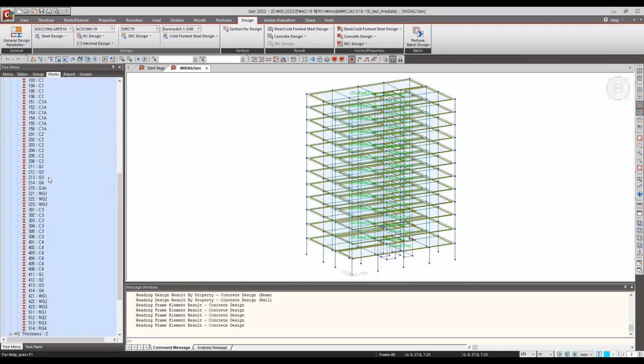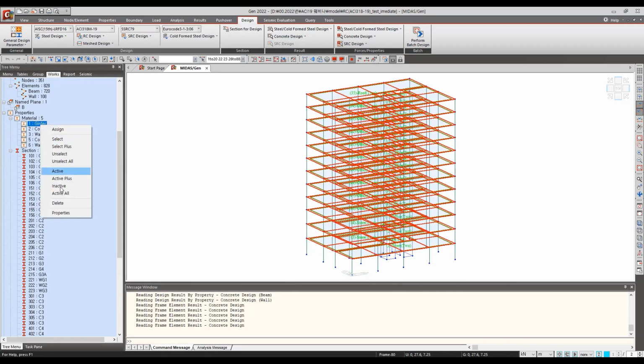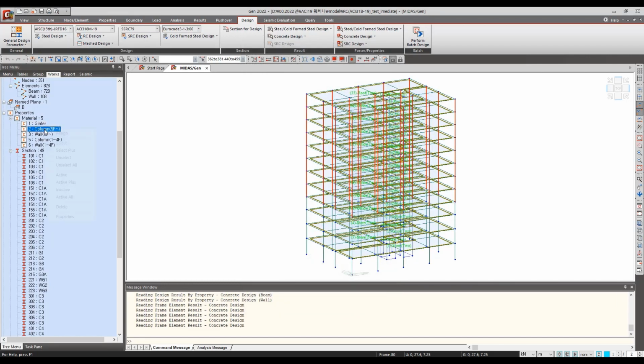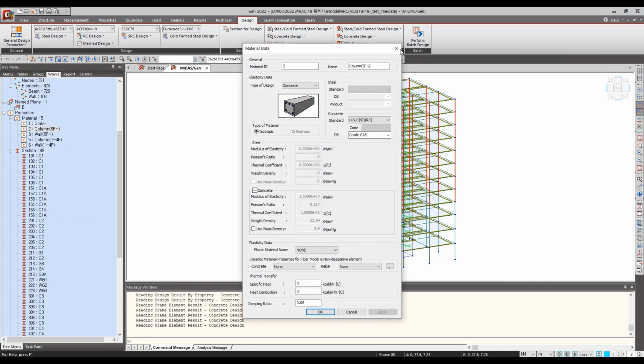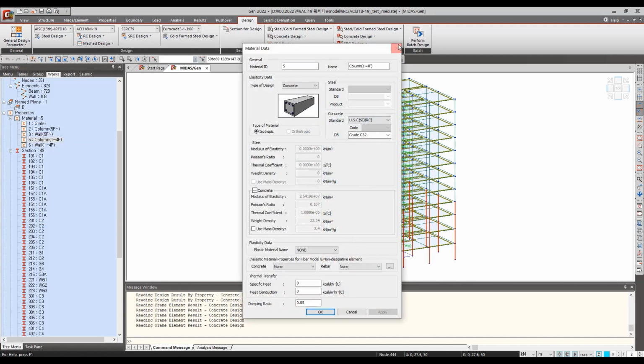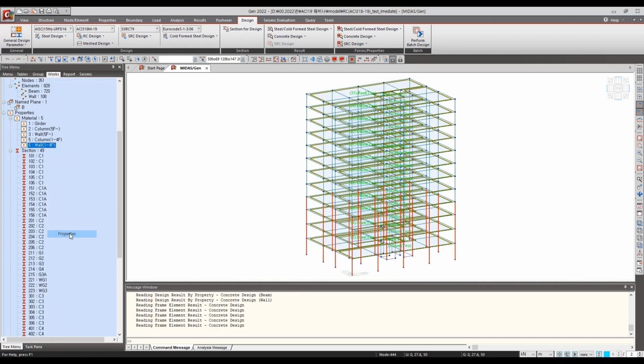For vertical members like columns and walls, C32 was used for the lower stories, and C28 was used for the upper stories and girders. The grade of main rebar is grade 550 MPa of design yield strength, and sub-rebar, grade 420. Longitudinal reinforcement over 515 MPa is not permitted for intermediate moment frames. So for the main rebar, we used grade 550, which is the maximum that can be used. In the case of special structural walls, up to grade 690 is allowed, but it is designed as grade 550 to match the type of rebar to the column.